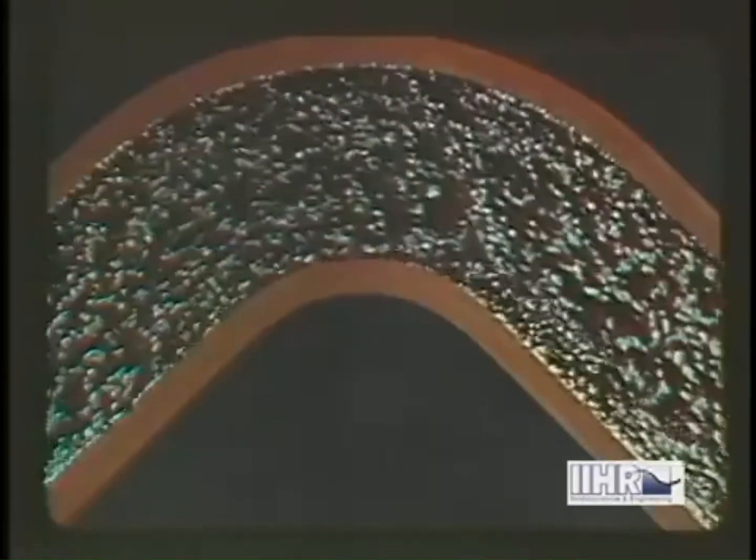Much the same elimination of separation is realized if, as is now beginning to occur, fluid is discharged tangentially into the boundary layer region through boundary slots. Even better results will next be seen to obtain as the boundary layer fluid is sucked into the slots as rapidly as it is retarded. A change in the pressure field as a whole.